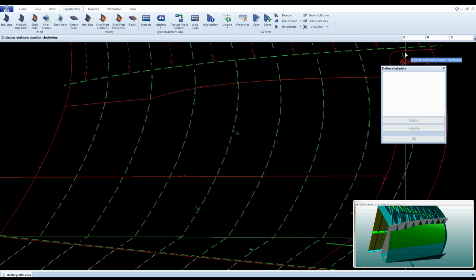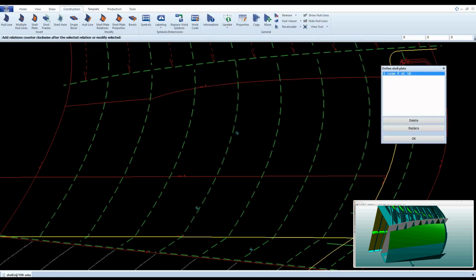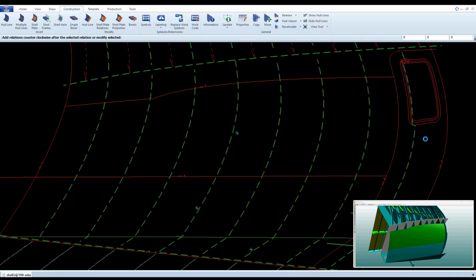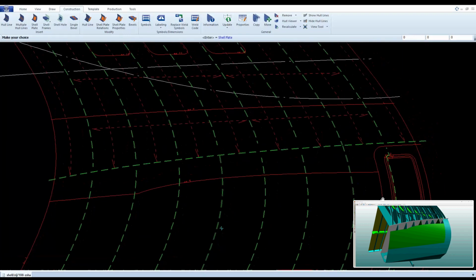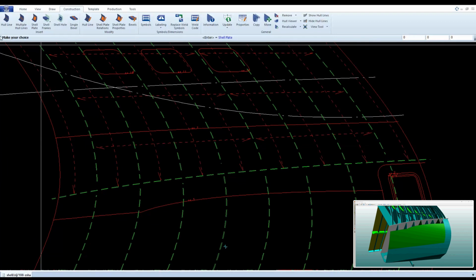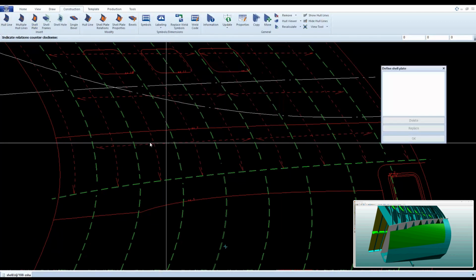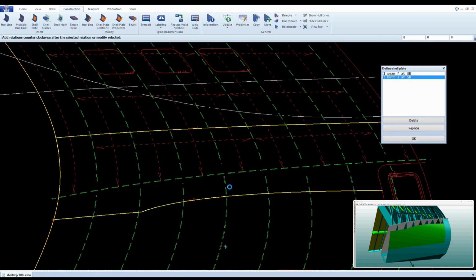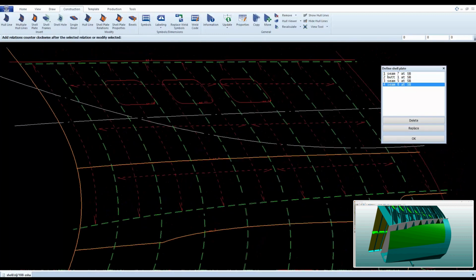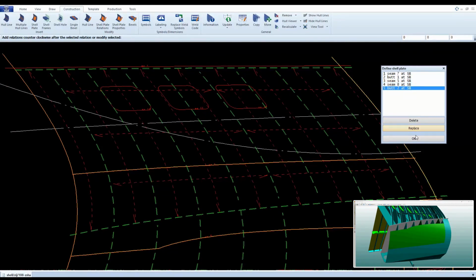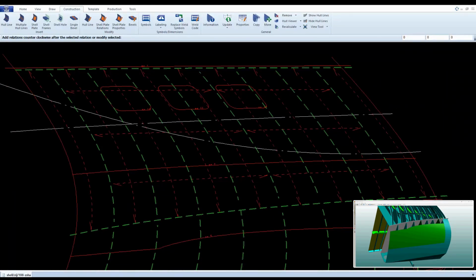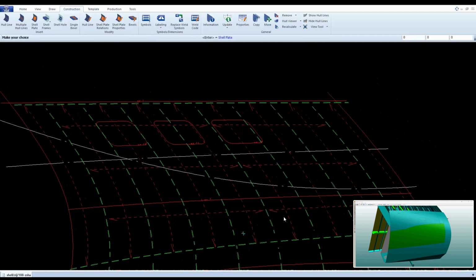Then I define the shell plate. Again, a shell plate with 3 borders. Press OK. The hull view shows the shell plate as well. And then again. Notice how this time I choose 5 borders. It doesn't matter, they could be 1 if it is a closed hull line, they could be 10, whatever is necessary.